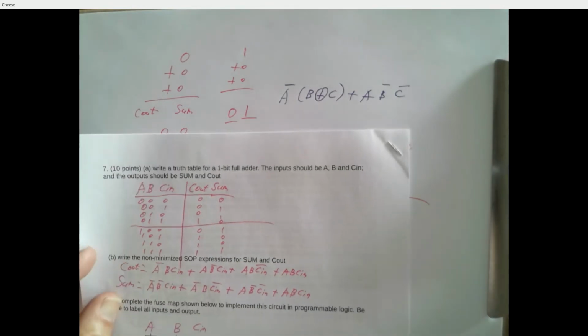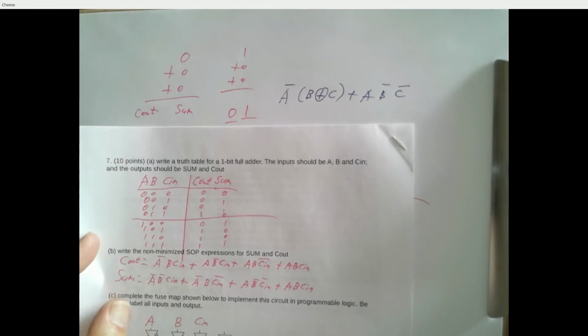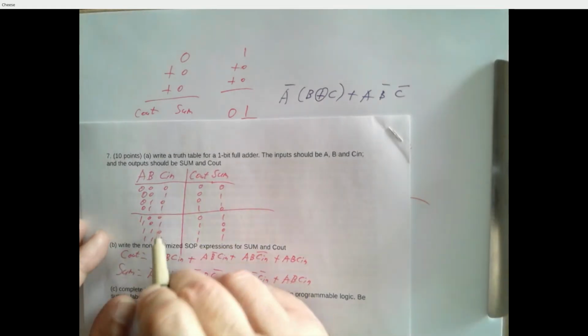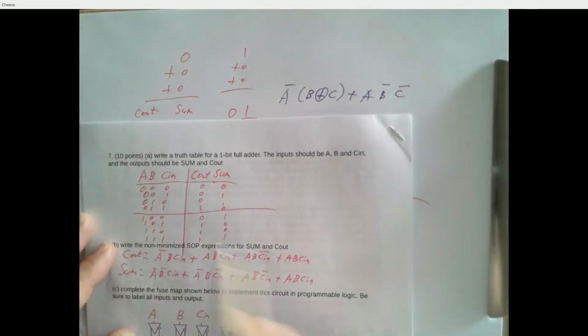How do we get the carry in of 1 in the second part, other than just counting in binary? Yeah, you're just counting in binary. When you make a truth table, you need to list every possible combination of all your inputs. Gotcha. And the easiest way, probably, once you know how to do it, is to just write out all the numbers in binary in order. But sometimes people just try to think out what the different combinations are and hope that you end up with 8 and that they're all different. But if you know how to count in binary, you can do that.